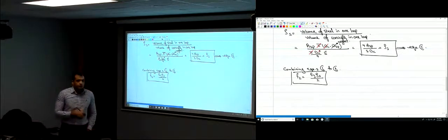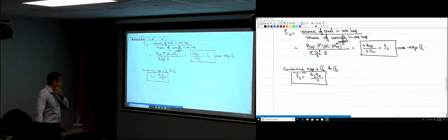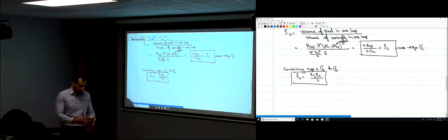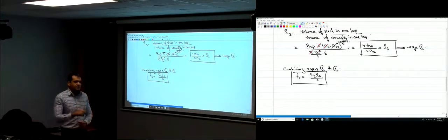Okay? That's the confining stress, the maximum confining stress due to the effect of the spiral. Now, when you confine the core with this magnitude of stress, that will increase the axial stress that the concrete can resist.